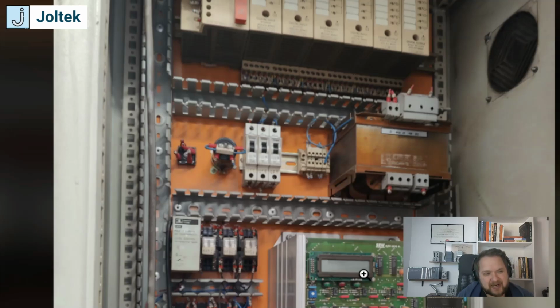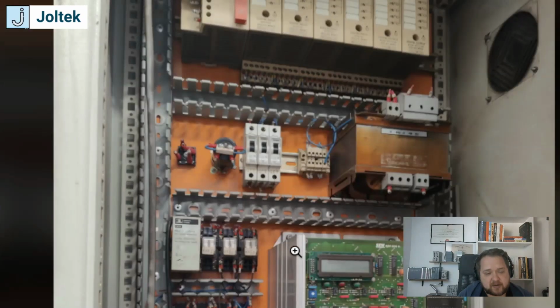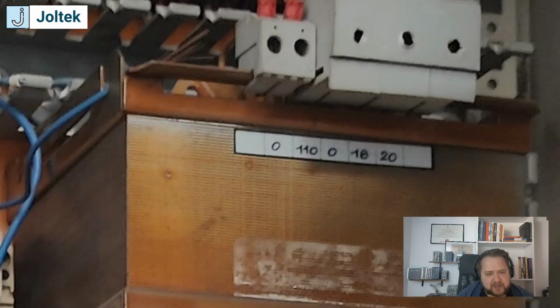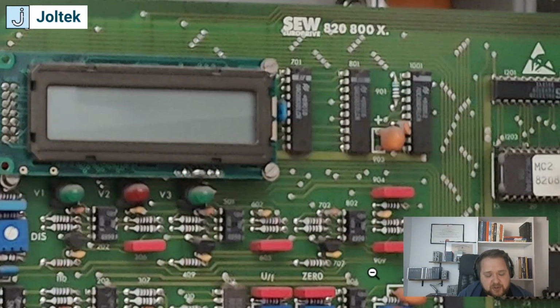So I would start by, first of all, figuring out all of the major parts that are part of the system. So in this case, we have a PLC. I'm not even sure what model of a PLC this is. It looks like it is a Simatic, so it looks like some kind of an older version of a Siemens PLC. Obviously a transformer should not be extremely complicated. It's probably going from 3-phase down to 110. And then we have this drive, which is looking incredible because it is all through hole components. As you can see here by the label, it's a SEW Eurodrive type of system.